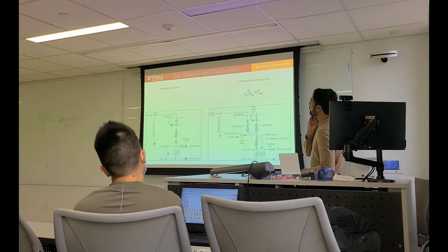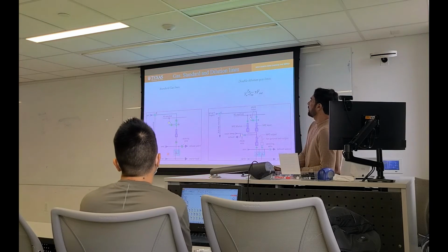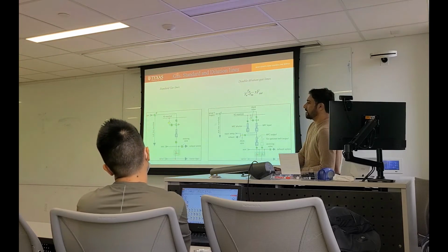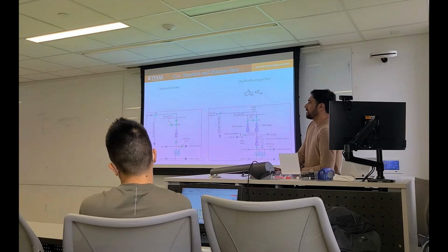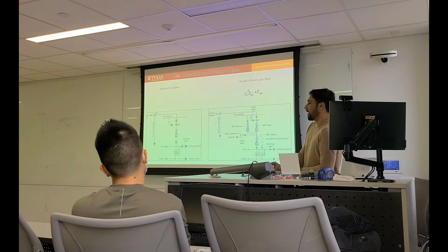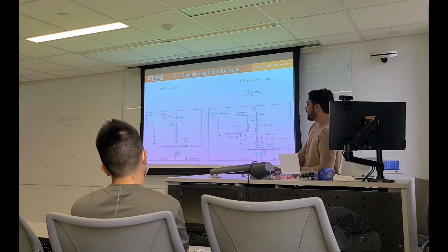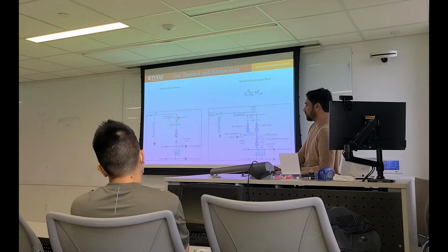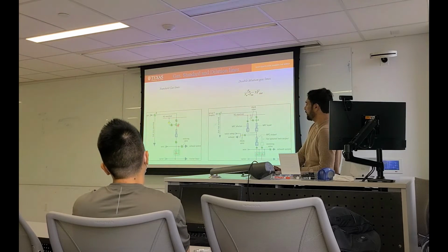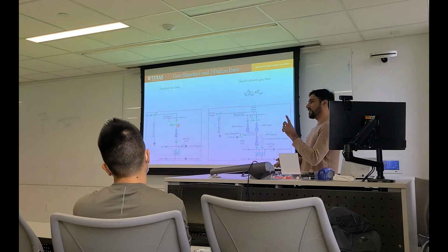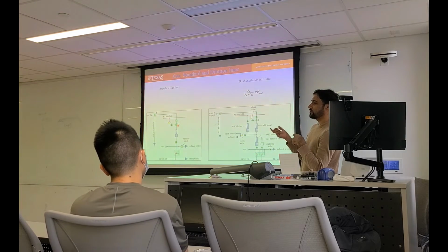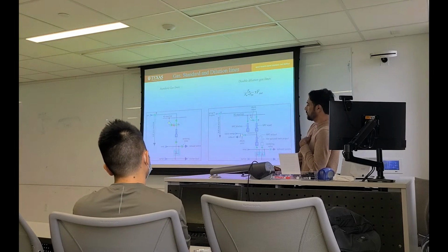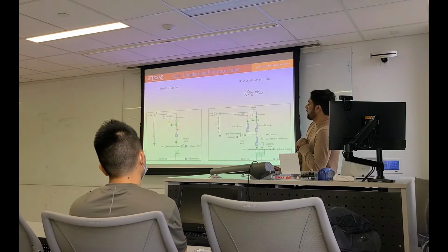So this is about the standard and dilution lines. First, I will talk about the gas. Why do we need dilution lines? Standard lines mean you just directly flow your gas. Suppose you have N2 or H2. These are normally closed valves. These are normally open valves. You can close them or open them depending on your need through the software. These are the pneumatic valves. This is the MFC. You can control your flow through the software.